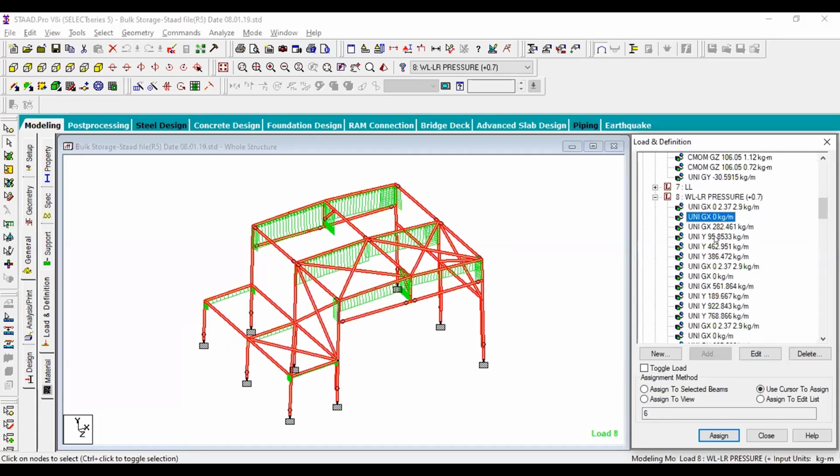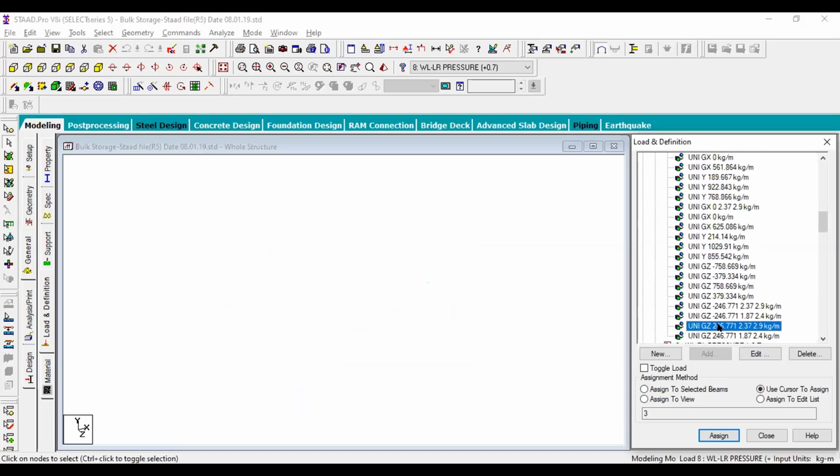Wind becomes very prominent when we have these open structures, because the wind gust might push your structure upwards, and since these PV structures are all connection based. I mean, the pedestal is of concrete, but the columns are all connected through bolts and nuts at the bottom here. So wind is a prominent load which acts on the PV structure. It might uproot the structure completely if you don't take care of the wind here. So wind analysis is very important in PV structures.